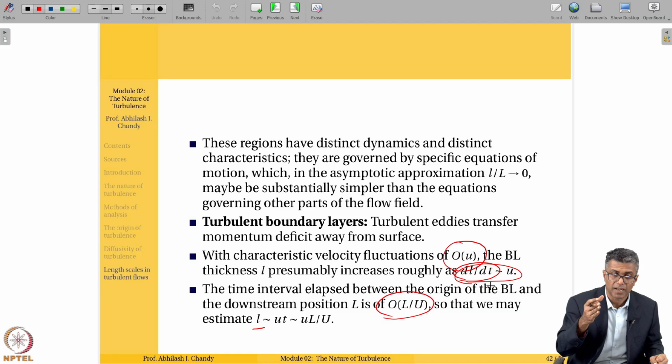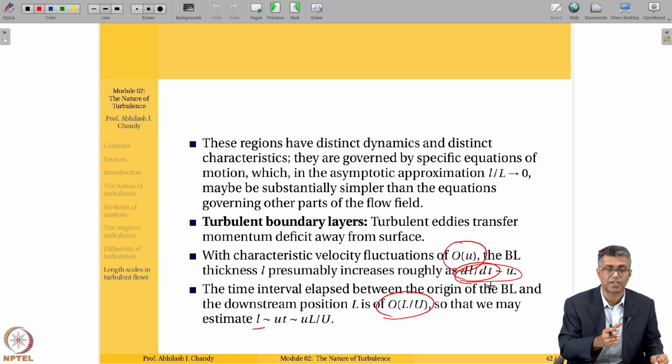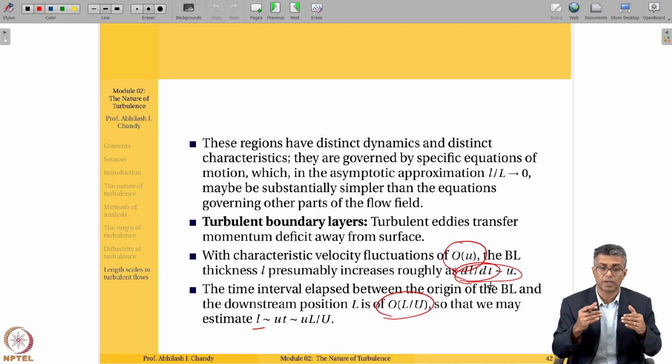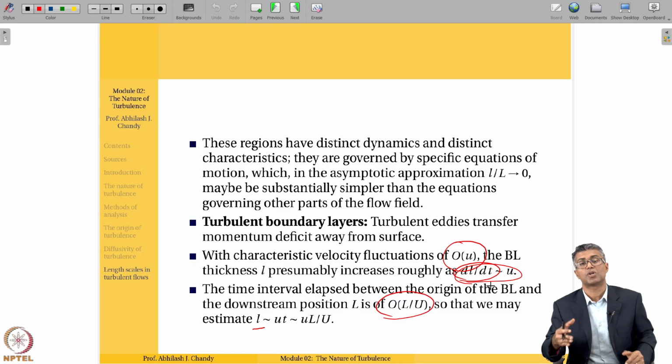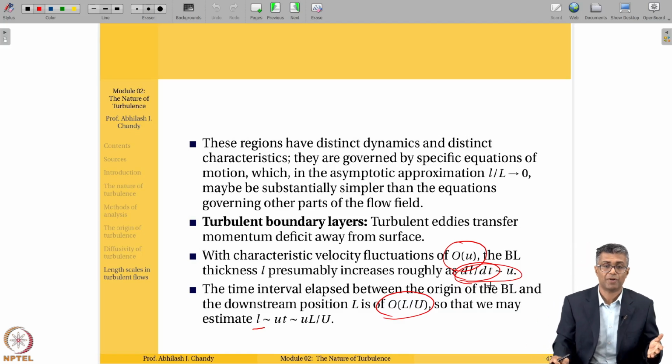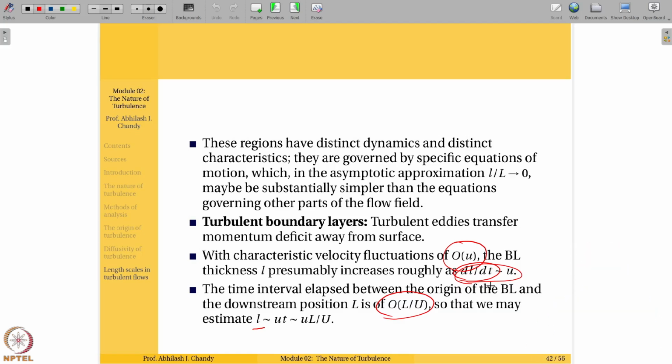We have taken the diffusive length scale and the convective length scale and tried to come up with relationships that are based on the ratios of these two length scales, and even better, we related these ratios to the drag coefficient both in laminar flow and turbulent flow.